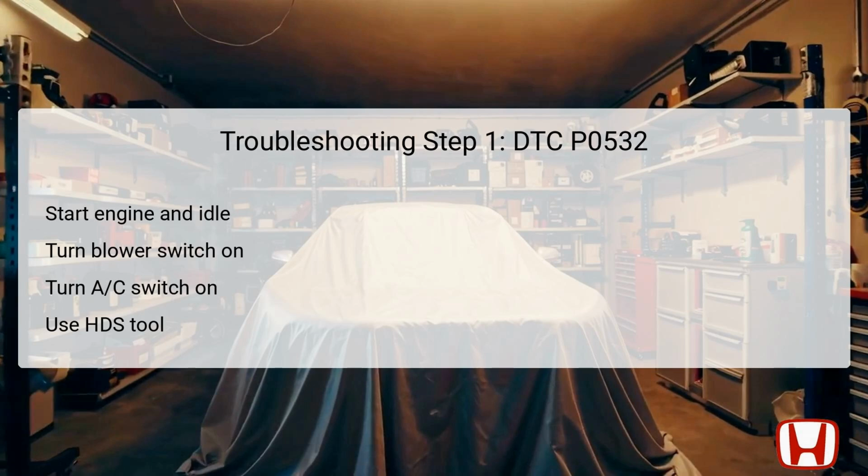You will specifically check the AC pressure sensor readings to ascertain if they are below the established threshold of 0.24 volts. If the current conditions match the threshold indicating low voltage, the failure has been duplicated and you will proceed to the next troubleshooting step. If not, you may need to check for intermittent failures or poor connections in the circuit. This verification process is vital to ensure that we are addressing the correct issue.